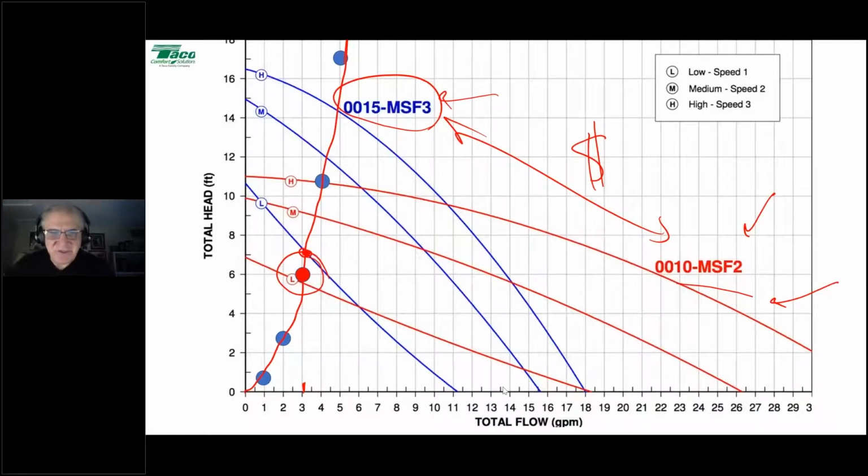A really good question from Steve Metlak. Does the number of zone valves in a system affect your choice of flat versus steep curves? No, it doesn't. If I have zone valves, I'm going to virtually always go with a flat curve pump. Flat curve circulators and zone valves go together like cake and ice cream. Steep curve pumps and zone valves go together like tuna fish and ice cream, meaning not at all.